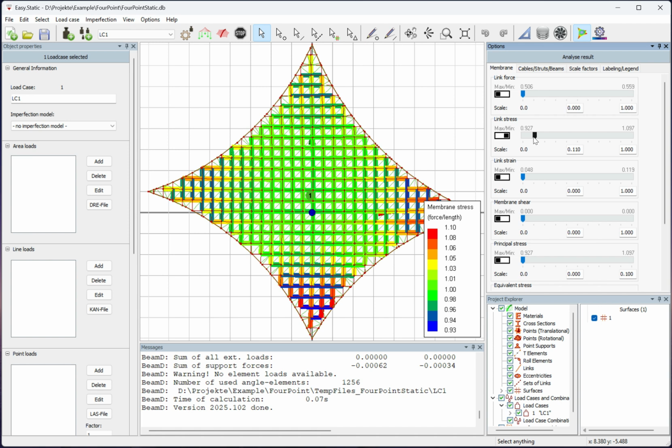The displayed stress distribution reflects the mesh property presets that were defined during the initial form-finding step covered in the first video. The legend displayed in the graphical interface shows the stress distribution using numerical values. In the pre-stressed state resulting from form finding, the value is close to 1, with only slight deviations at the high and low points. The previous calculation was solely used to verify the form finding result.